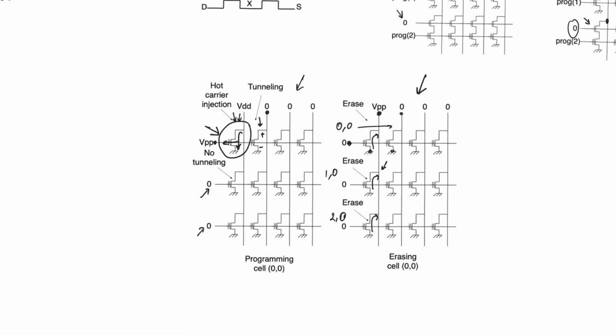But this is an important conclusion that we reach here, which is that if we insist on having a single transistor per storage cell, then we have no way of erasing a single cell. And we have to accept the reality that when erasing a single cell, we would have to erase all the other cells, at least in the column that share the same bit line with it. This is actually the foundation of flash memory, which is the most important and most practical category of non-volatile memories.